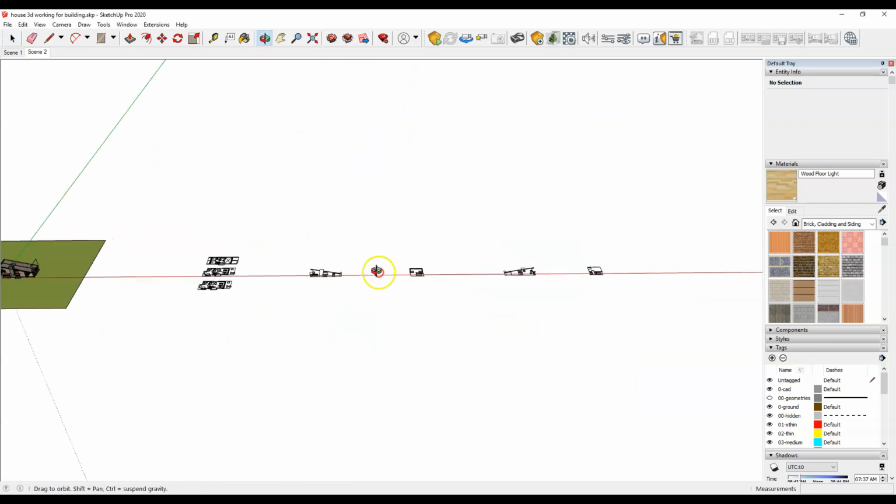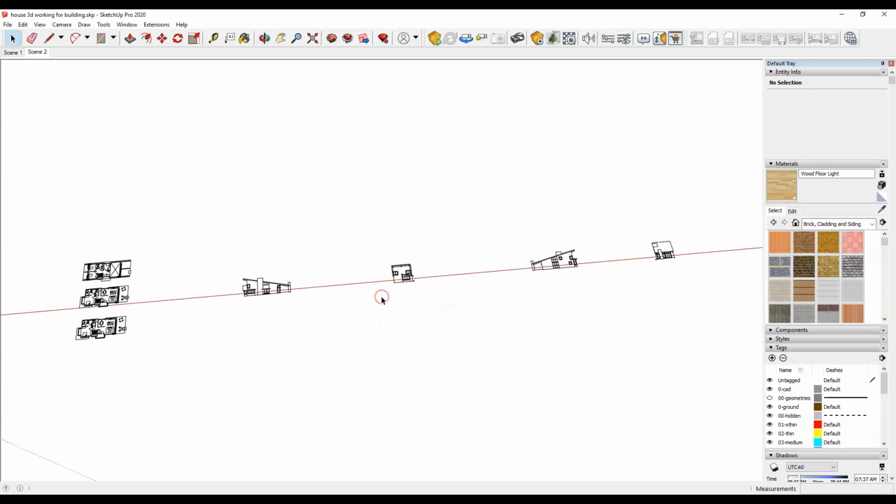Basically, you'll have, of course, the CAD plans and elevations already coming into this. And so what you want to do is import those CAD plans and elevations. Again, it's pretty simple. Any of the technical stuff will be in follow-up videos, but we have them here. The first thing you basically want to do is build what I'd call a framework around at least the first floor plan. You're just going to use the CAD work to create a basic 3D model. It's not really a 3D model, but it's a scaffolding, a framework about which you can model the rest of the project. A few simple steps and you're good to go.